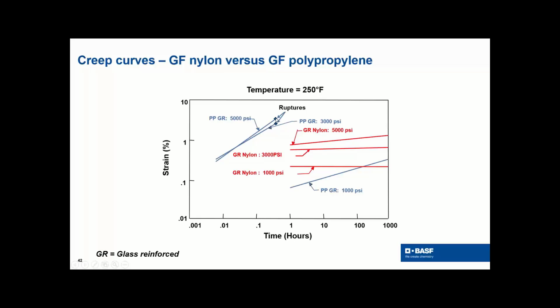say you're replacing that metal shelf with plastic, it's going to fail within minutes. It's going to be a real quick failure. Well, let's change the design. Let's make it 3,000. We're going to make that shelf a little bit thicker. Boom. Well, it still fails. Now we're going to make it really thick, and we're going to make it down to 1,000. Well, it's better. It survived 1,000 hours, but it's only a matter of time before it's going to fail. So the better choice is to go to a high temperature material that can withstand that temperature too.